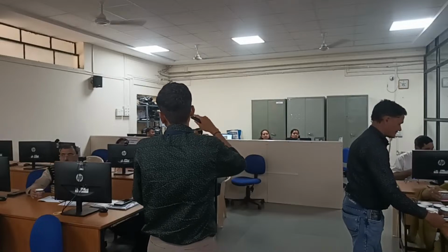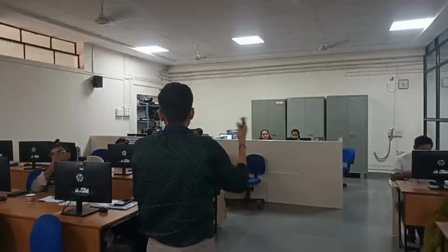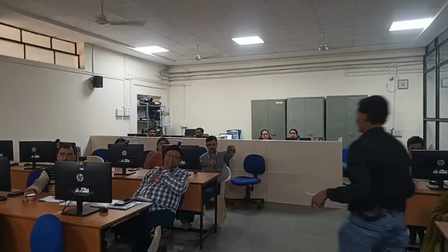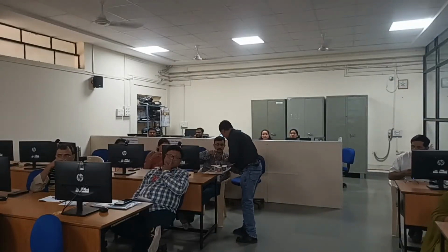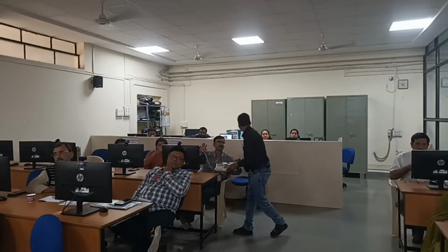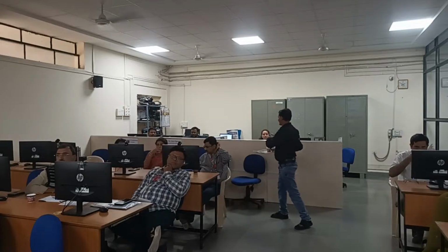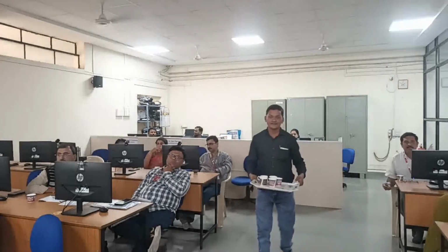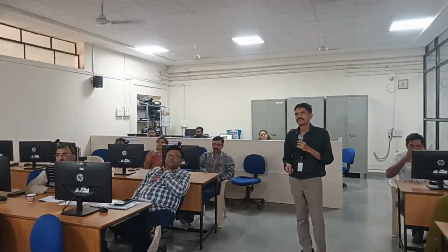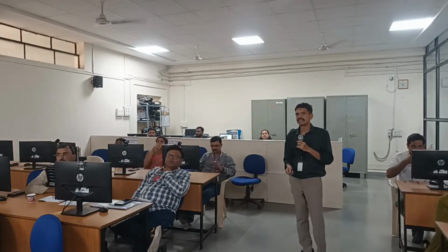So with all those concepts, you design the filter with LC only. Then you transform: an inductor becomes a series transmission line, and a capacitor becomes an open circuited microstrip line. What is this? Can you guess? Let me go back to a clearer picture. Can you find inductors and capacitors in the matching networks in this picture? See, these are capacitors. This is also a capacitor. This 50 ohm transmission line 2 is an inductor.